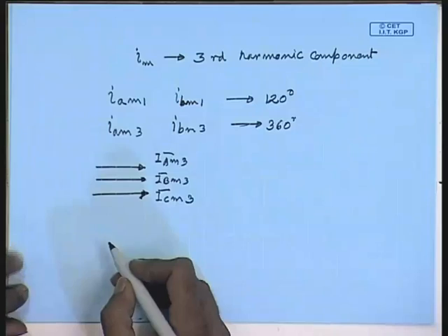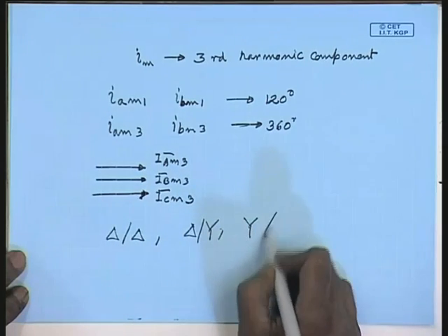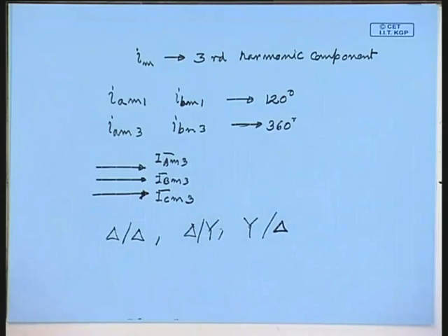So, the preferred winding connections will be delta delta, delta star or star delta, of which we have seen that if one side is very high voltage, then that side should preferably be star connected, and the other side may be delta connected. So, from the transmission level, the high voltage side winding will usually be the star connected winding, while the other side will be delta connected. The delta-delta winding is used specifically for low voltage transformers that need to supply a very large current, because in a delta-delta winding the winding current is less than the line current, therefore, the cross section of the windings becomes smaller.